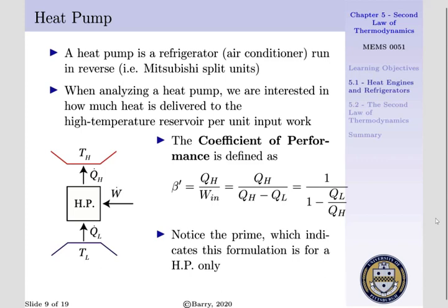Lastly, we have to talk about heat pumps. A heat pump is a refrigerator, i.e. an air conditioner, that is run in reverse. An example of this is Fujitsu or Mitsubishi split units. Now, heat pumps are like a refrigerator in that we are taking heat from a low temperature reservoir. This is typically outside your house, and then we are transferring it to a high temperature reservoir, i.e. the warm space inside your house.